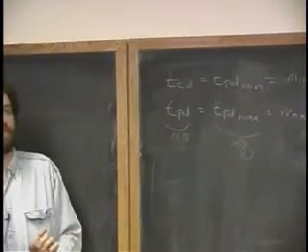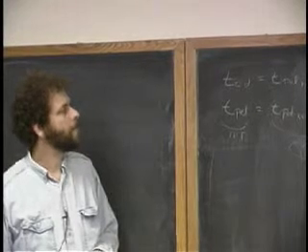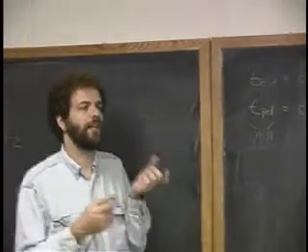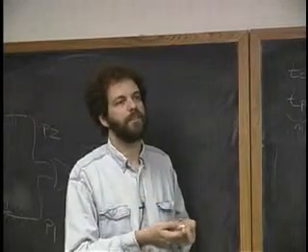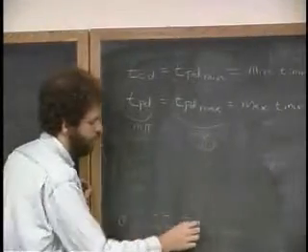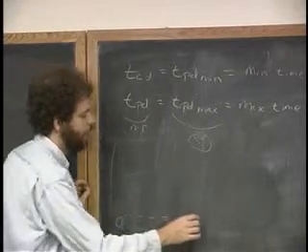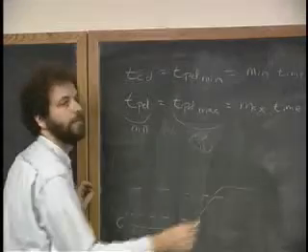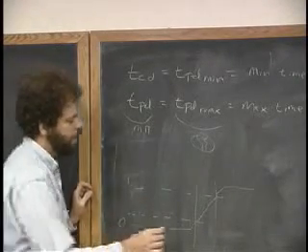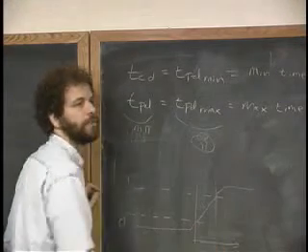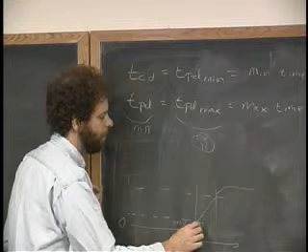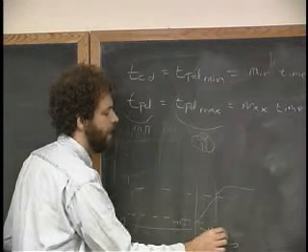If TCD isn't included in TPD, why is it called TPD min for TCD? I mean, it would make sense if it was actually part of it. Both of these things are due to the effect of signals propagating through a circuit. Okay, the question is what kind of signal do we mean? And in general, a signal goes from being a 0, okay, and then crosses a certain threshold where we say we don't know what it is. And then it goes and crosses another threshold. We say, okay, now we know that it's a 1. Okay? And during this time, we say it has an intermediate value that we're not sure of. And so the idea is that here is where the contamination starts to go into the circuit. Okay? And so we measure the TCD from the time when things go from valid to when they first become invalid, and then they become valid again.